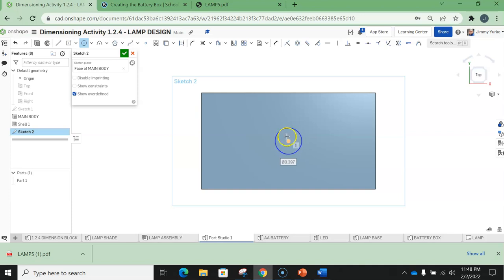Click, and remember there were two circles. One was 300 thousandths, so decimal point 300, enter, and add another circle from the same center point. And so long as that dimension box you see is still white, just a little quick tip here, you can just type a value.